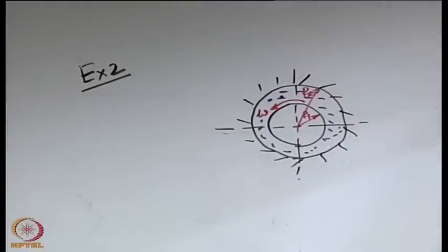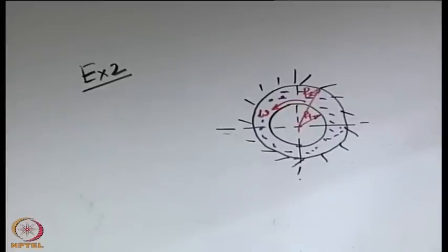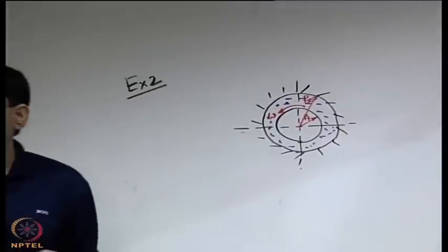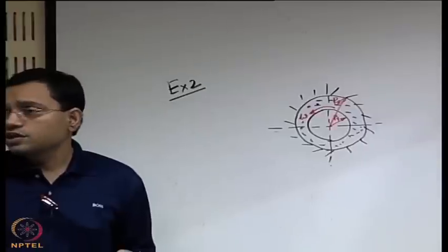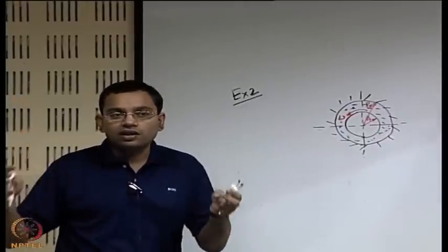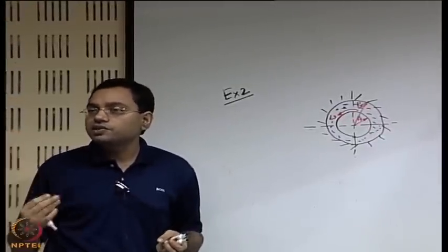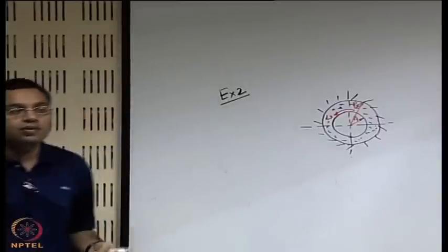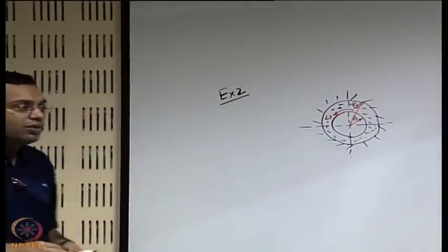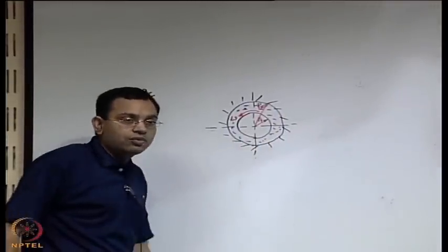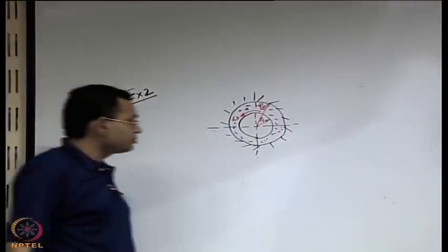That is the objective of analyzing this, and therefore, if we apply that particular torque and see that it is rotating with a uniform angular speed, that may be measured by something like a tachometer, then it is possible to relate these two in terms of the viscosity of the fluid. So, everything else being measured, from that expression we should be able to evaluate the viscosity of the fluid. That is the basic principle by which one may measure the viscosity of the fluid that is there in between. Typically this gap is very narrow, and we will see what is the consequence of that narrowness.